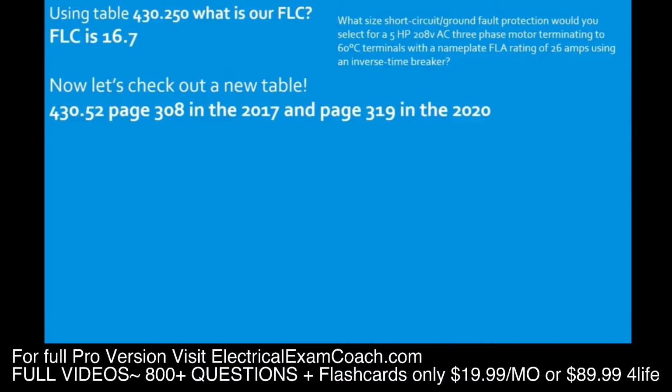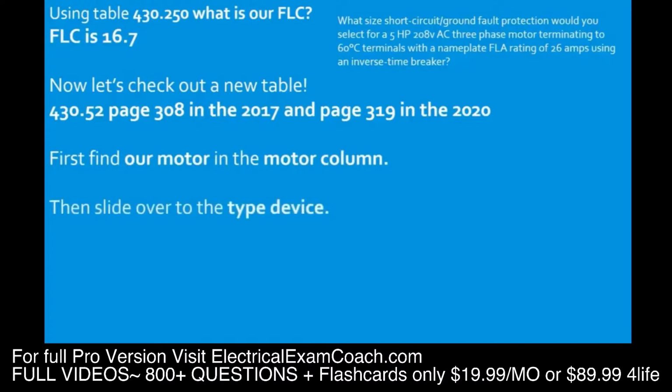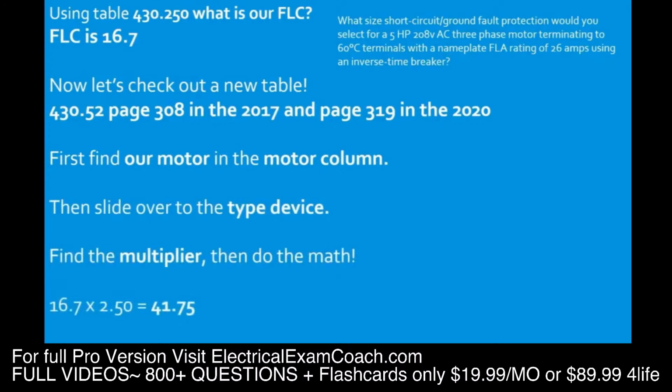So let's go ahead and answer our question. First, we find our motor in the motor column. We go down to polyphase. I want to let you know that that just means three-phase. Now we come over and tee off with our type of device. In this question, it was an inverse time breaker. Now what we do is we take that multiplier and do the math. We take our FLC, which is 16.7. We multiply it by 2.50. That is going to give us a new amperage to size our breaker by of 41.75.